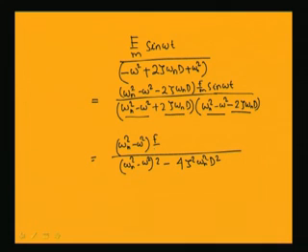In the numerator part it will be equal to omega n square minus omega square into f by m sin omega t minus 2 zeta omega n. This d operator is nothing but the differential operator. So, one can differentiate that thing. So, one can obtain 2 zeta omega n into omega. So, the differentiation of sin is cos. So, this is cos omega t into f by m.